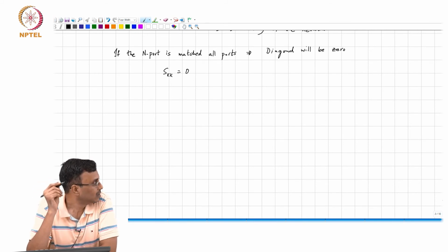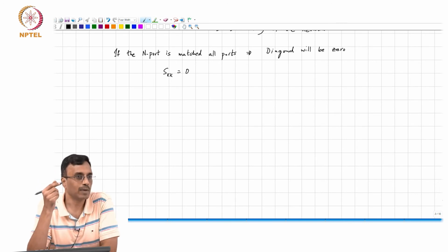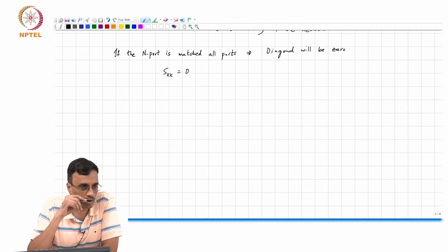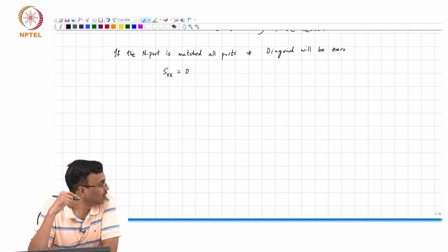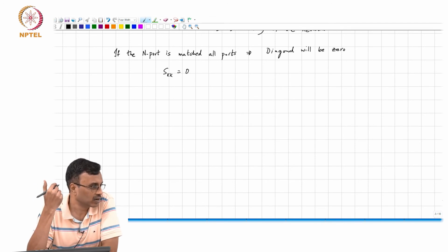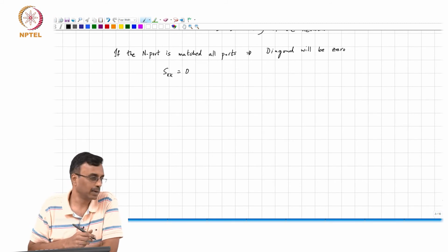All right. And remember, we started off this entire discussion of S parameters by saying we wanted to measure Y, but then we found that to be a practical difficulty. So we came up with a new parameter set, the S parameter set. Now the question is, how is the S parameter set related to either the Y or the Z or any of these a bazillion other things? So let's just do, say for instance, how the S parameters are related to the Y parameters.